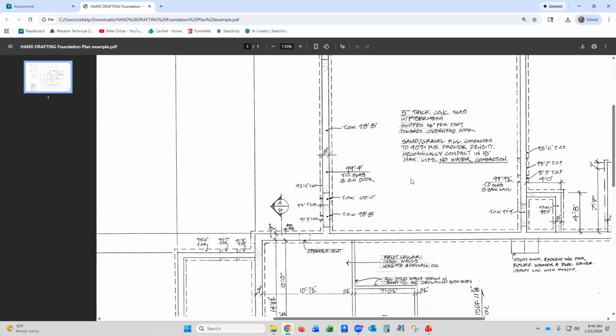Okay, so here's my basement. Way down low. There's my footing, and there's my basement wall, and here's my basement floor. My garage slab is up here in this neck of the woods. And my garage, how far does my footing need to be below my garage slab or my grade? My grade's about here. Because I'm driving in at grade, remember my grade's got to be a little bit below all my wood. So I had it 8 inches below all that wood. So my garage floor is going to be here. So this is where grade is, because I don't want to drive up a big hump to get into my garage. So this is the edge of my garage.